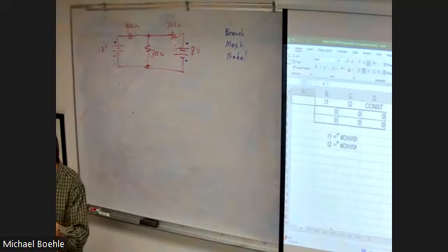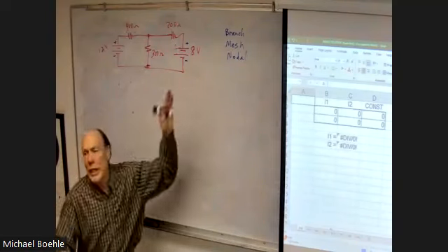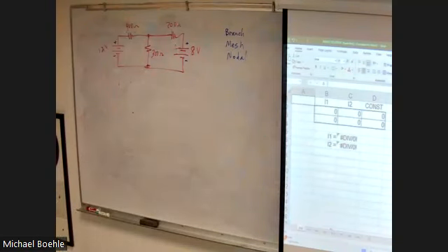Polarity of my sources doesn't change. So now we're going to look at mesh analysis, right? Mesh analysis. So with mesh analysis, the currents we're going to draw are what are going to circulate in those panes that I talked about. So we said earlier we had how many panes? 2.